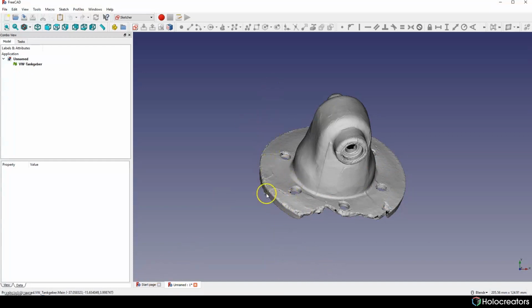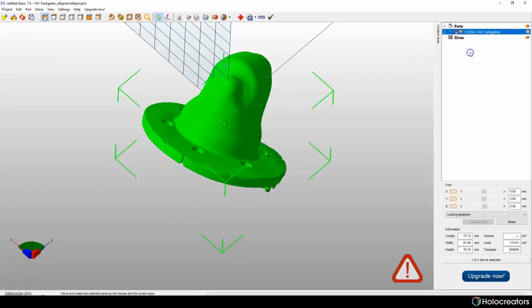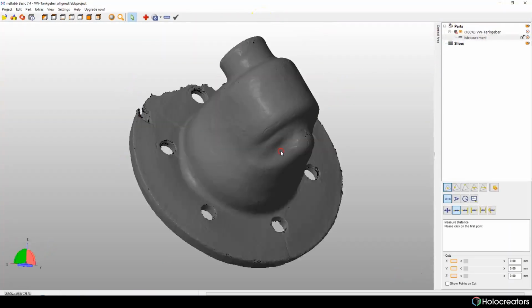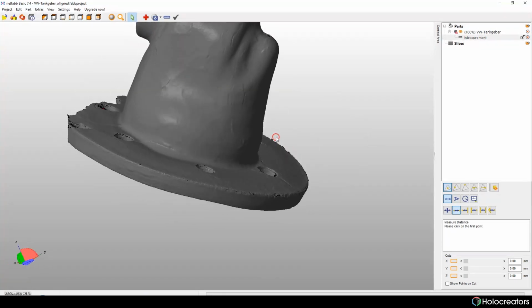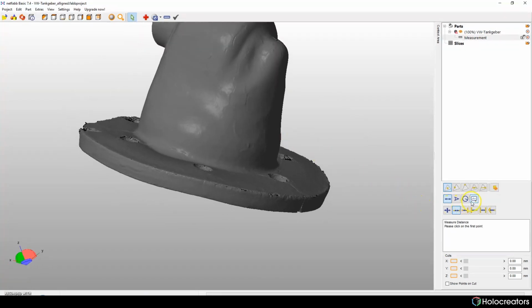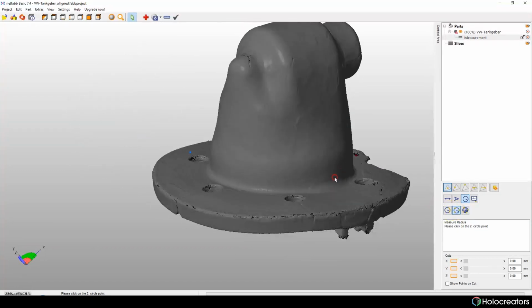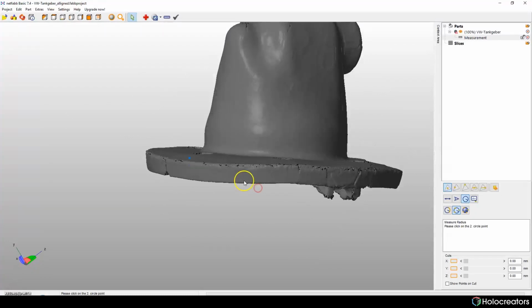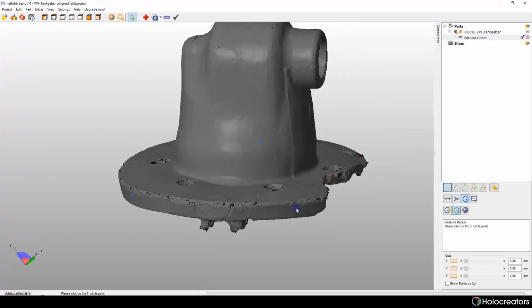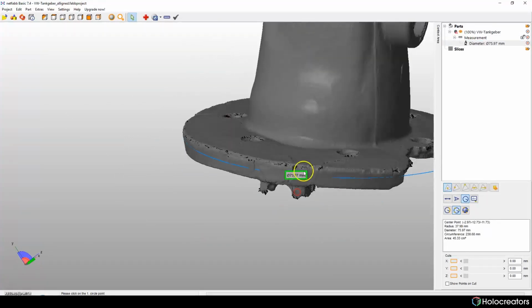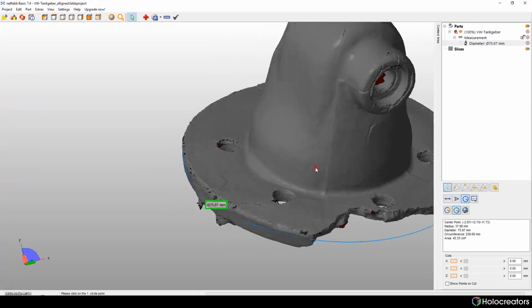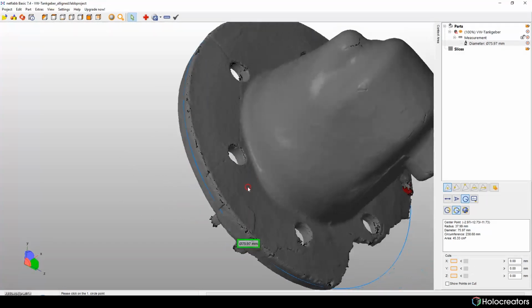We can measure the outer diameter in the NetFab tool. We have to choose our model, press this icon to create a new measurement, and then choose this tool. By placing 3 vertices on the surface, we get the outer diameter of the flange.